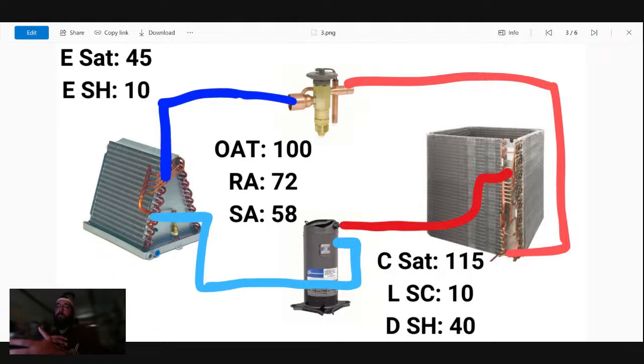can cause the moisture to wick off of the coil and never even make it to the drain pan. So you end up literally just, your refrigerant condenses it, and then the airstream just sucks it right back into itself and carries it on downstream. So that could be a real issue there. So yes, make sure your condensate and all that are in good shape and properly installed.